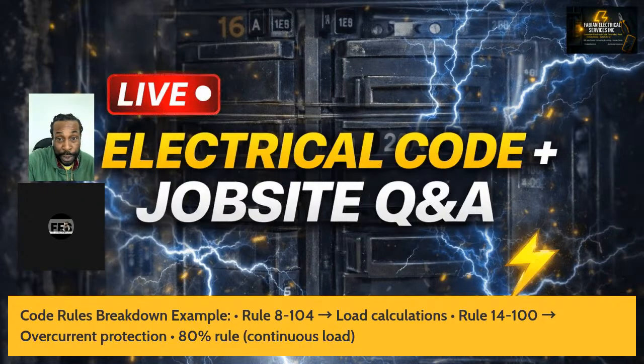Okay, so that's the code rule breakdown examples. It says Rule 8-104, load calculations, and Rule 14-100, overcurrent protection. The 80% rule for continuous loads. When you're loading your circuits, there is an 80% rule that you have to keep into effect, and you cannot go over it. The 80% rule is vital for the whole circuit to run correctly. When the circuit runs smooth, you have no overheating and so on, and you don't have any of your breakers tripping.